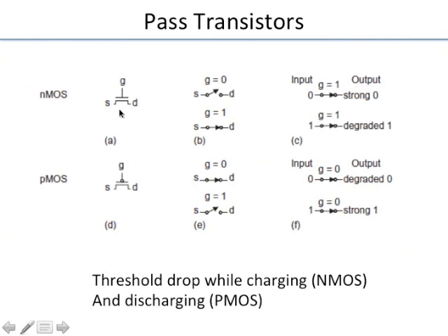Let us think of the situation where G is 1 and S goes to VDD, logic 1. Now the D side also starts charging up, because G is high. Now which is the gate in that situation? Which is the source? It's labeled S and D here, but really the current flow is like this. If the left side is VDD and the right side is ground, the charge will flow like this. So really the node labeled D is actually the source.